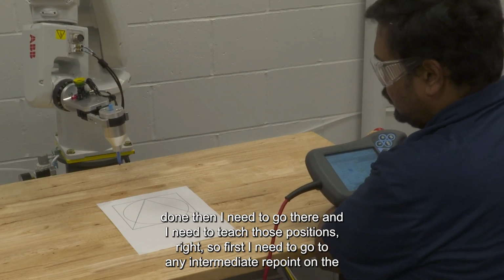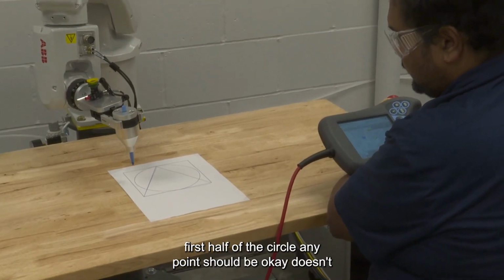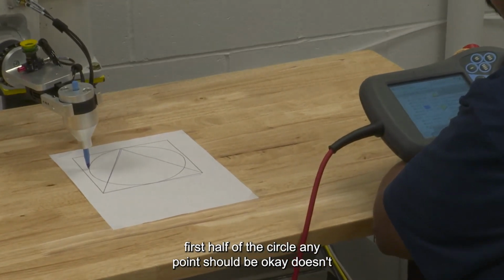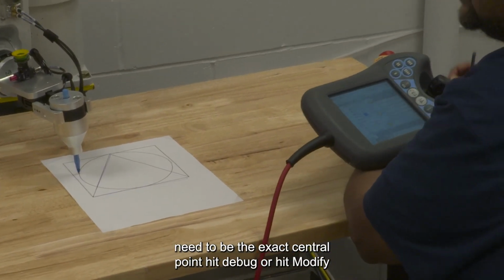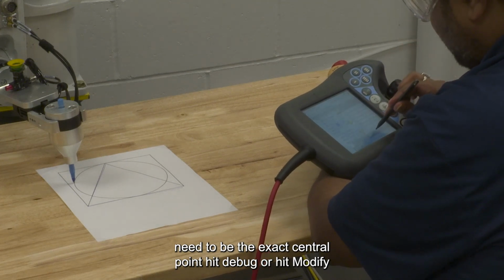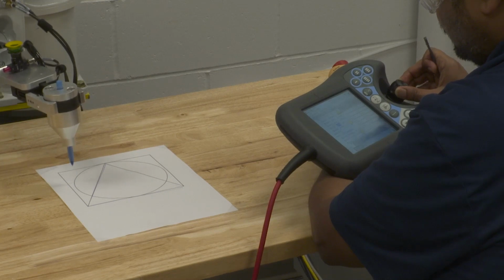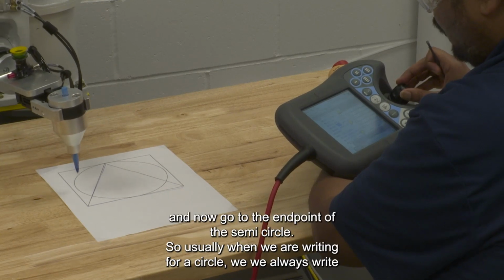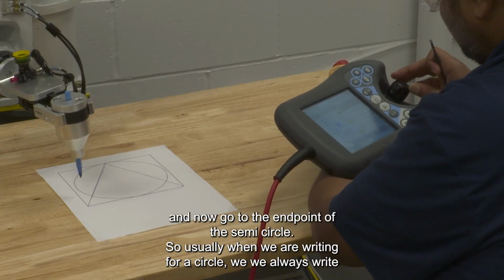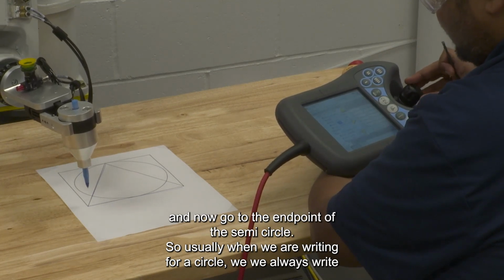So first I need to go to any intermediary point on the first half of the circle. Any point should be okay, it does not need to be the exact center point. Hit debug, hit modify position, and now go to the end point of the semicircle.